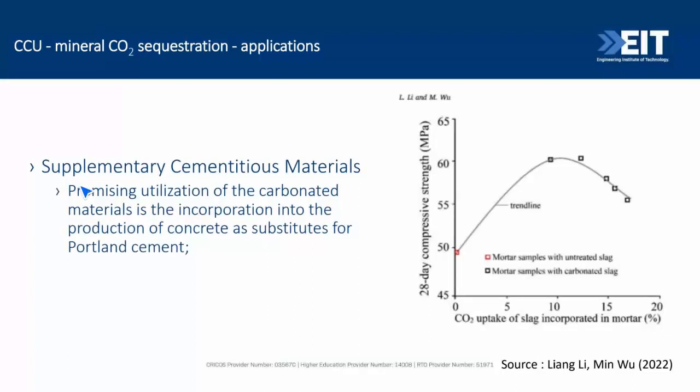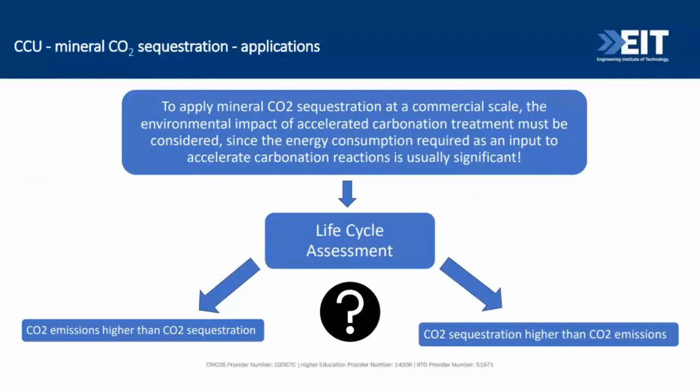And this one is interesting, when you are working with supplementary cementitious materials. This is an example of carbon dioxide uptake of slag. You can see here a very simple example where you have the mortar with the untreated slag, and here the carbonated slag. It's a significant improvement, right, when you compare. So everything is to show you that it's possible, right? That's why the industry is targeting this and supporting it. I can tell you, the cement industry is having a lot of collaboration with different universities around the globe just to try to find positive solutions.